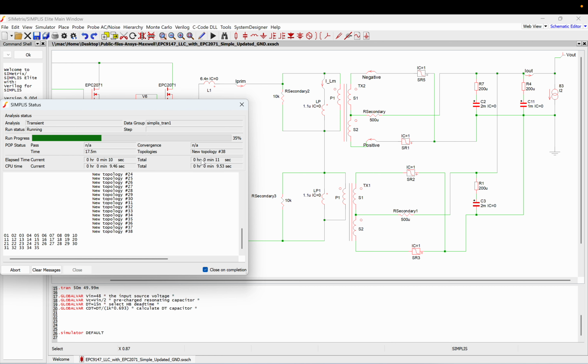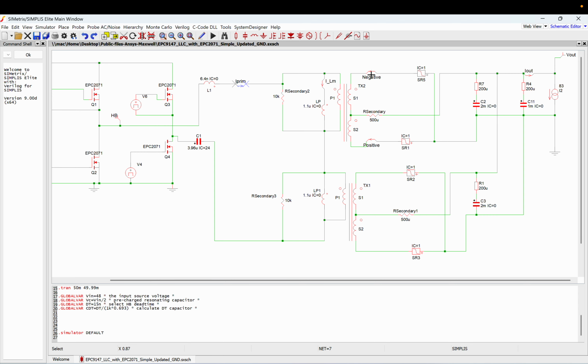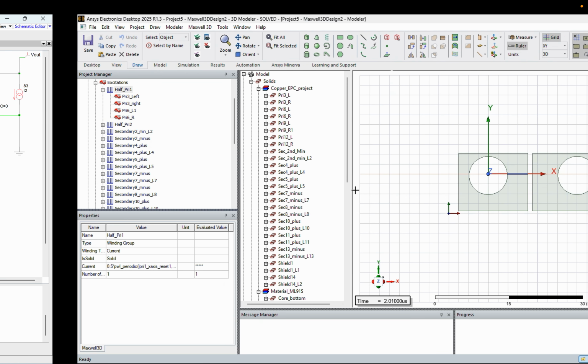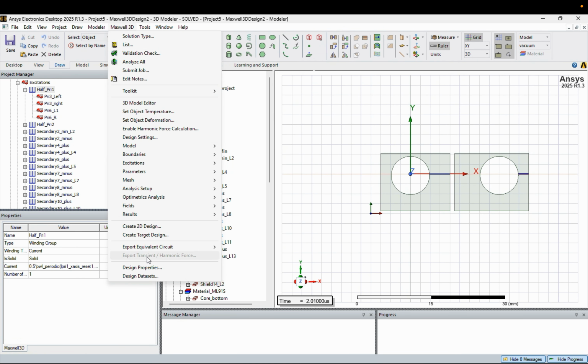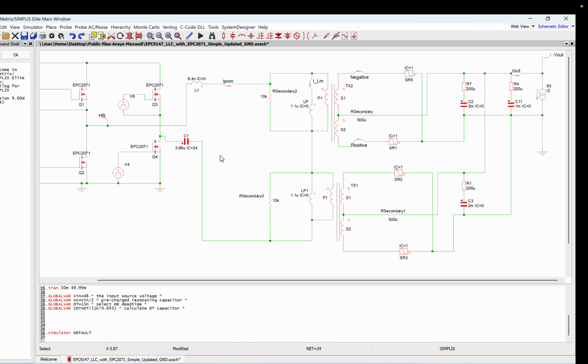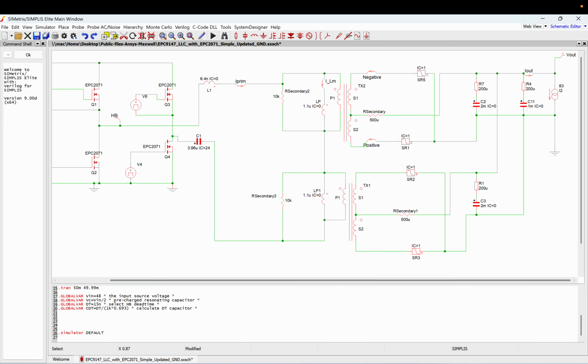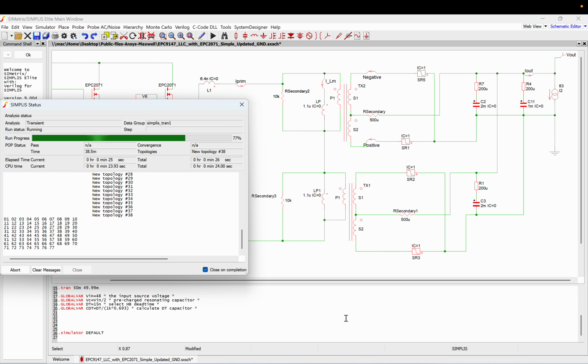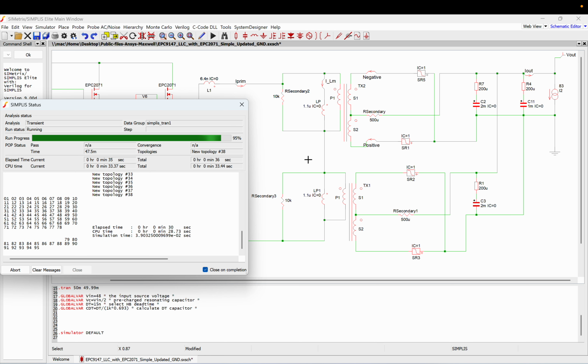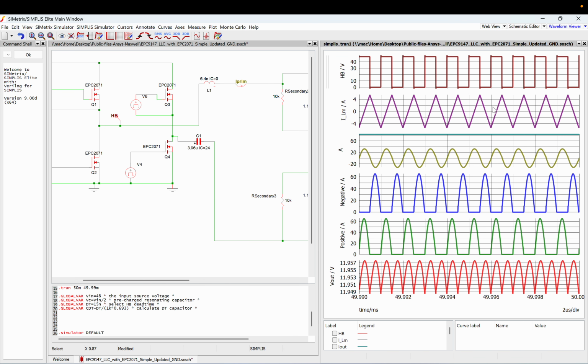So you try to get the waveforms from here, the primary waveform and the secondary waveform, and I just put it in design datasets. Now there's one caveat here. Let me show you what that is. So this is operating at the resonant frequency, 1 megahertz. You have 12 volt, 83 amp. This is how the waveform looks like. Output is regulated at 12 volts, perfectly ideal.